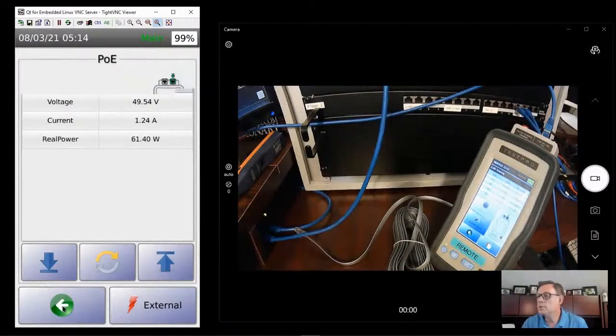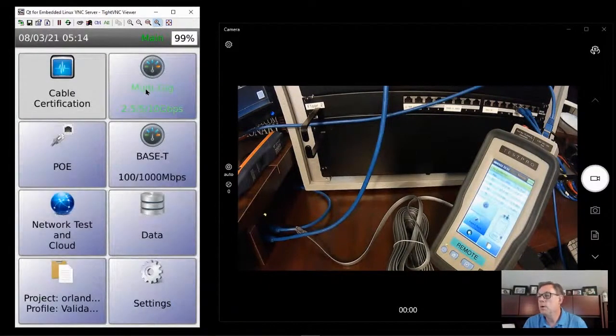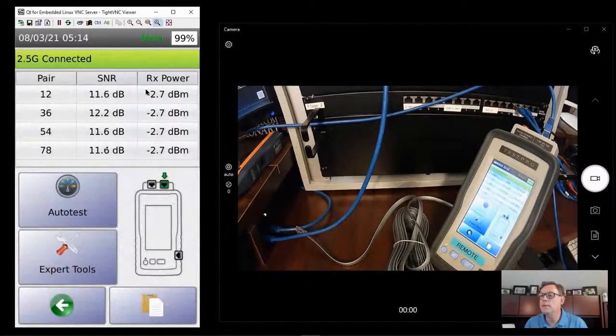And beyond just troubleshooting the PoE, you probably also want to look at how that link is performing. So imagine we're testing back into a switch. It'd be the same process as what I've got going on into my unit here. So you could do an end-to-end test like this with the 2 test pros, but more often you would do it with a switch on the far end. You're just connecting where the powered device is and testing back into the switch.